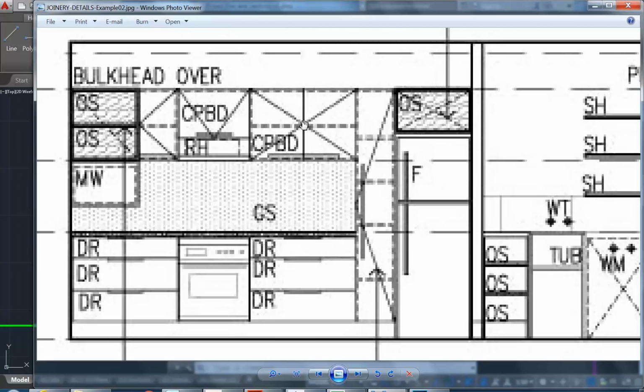So they open, the handles at the pointy end. Yes, and the round, it's called at the middle, it's the shelf. That's right. That shows the shelf height, but it doesn't show what's happening going the other way. So you need to show the section of the side. Yeah, that's right. And it's fairly easy to do the section though. Once you've got all of that, you just project off to the side. So just make sure you put chevrons on the doors to show which way they open.